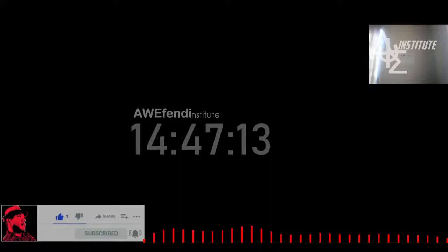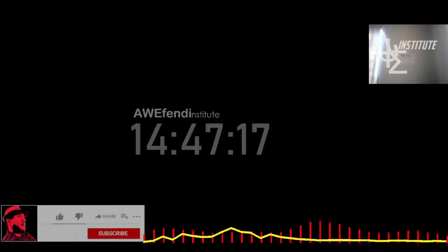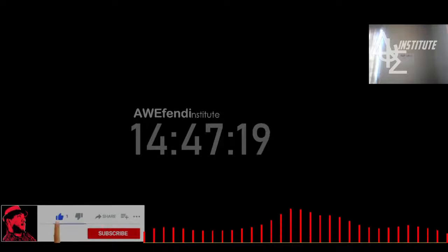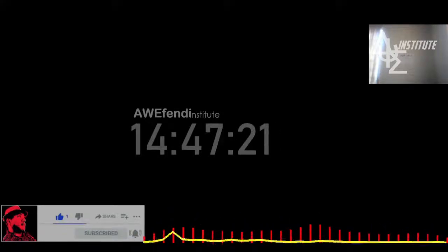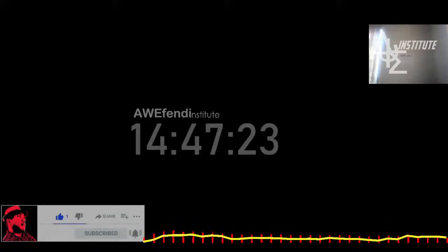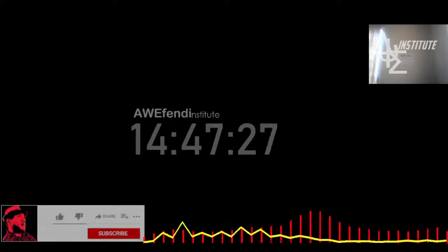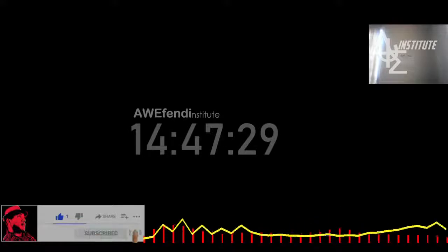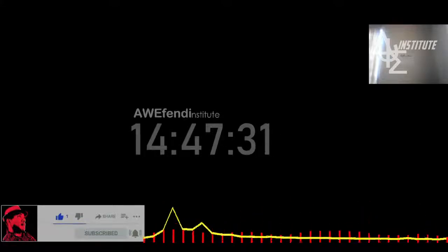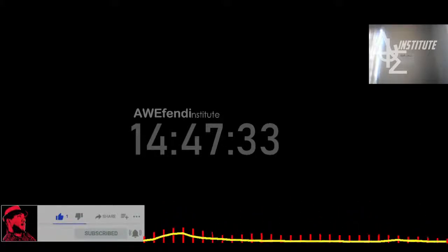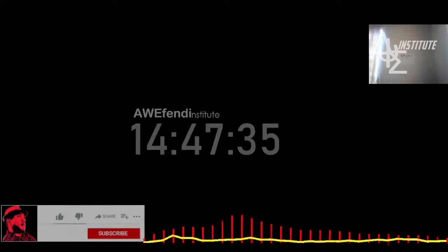71.4. But an interesting thing to see is, okay, what is the heat flow on the opposite face? And if we click, we can plot it there as well. And we can see that on the two faces, on one we have minus 71.4 and the other one 71.4, showing that there's energy balance and any heat coming into the geometry equals the amount of heat coming out.